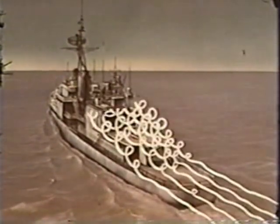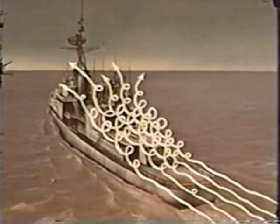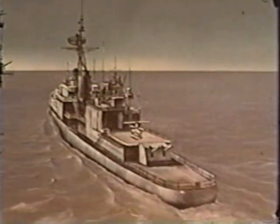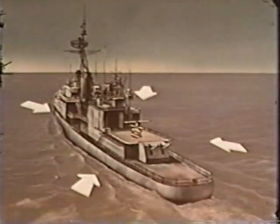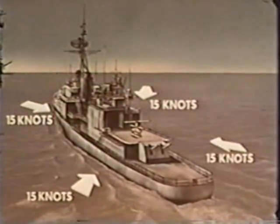If the wind is directly astern, there is also a good deal of undesirable vertical effect. Also, if control is lost, the drone could be blown against the hangar or other parts of the superstructure. Wind off the beam also causes turbulence around the deck. For optimum operating conditions, relative wind velocity should be about 15 knots, preferably on the bow.